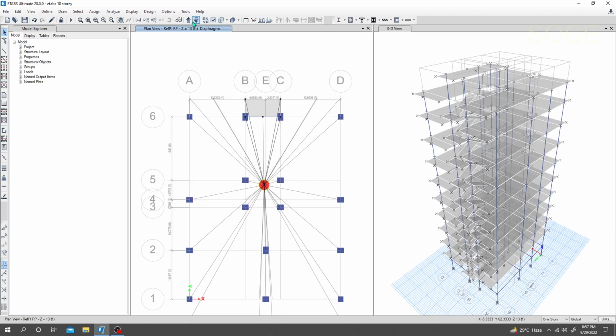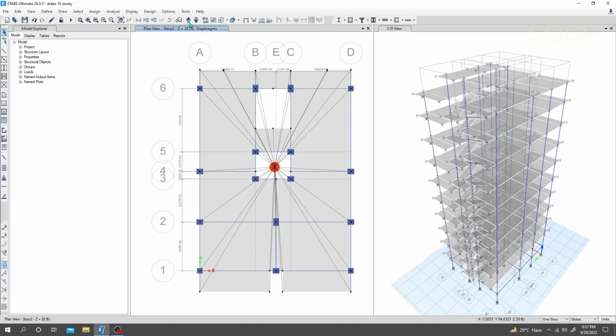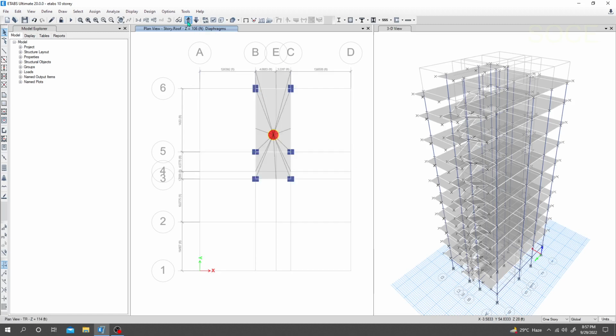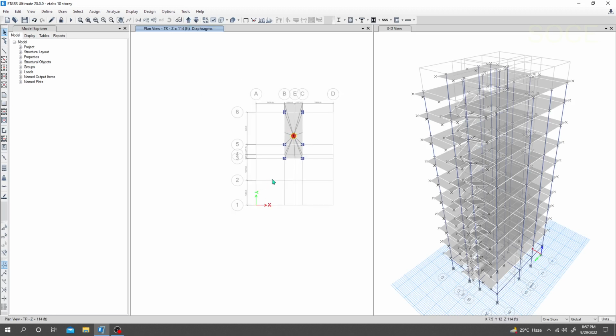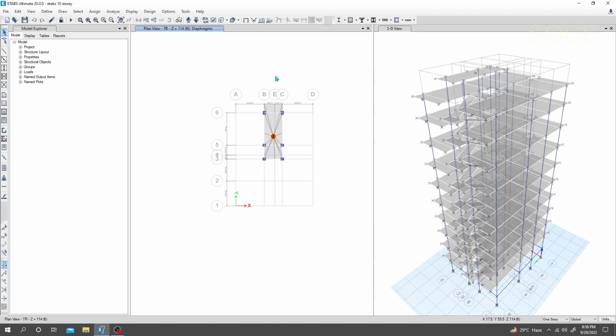Okay, now go top, just see, this is our diaphragm. See here all points are almost the same, and terrace here, this is the center of our diaphragm. So when it's done, now we are almost ready to assign. Now I'll save that model, and we're ready to define our earthquake and wind load. So in the next lecture I'll show you how we'll define our earthquake load, and after that we'll go for analysis.